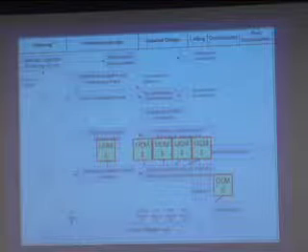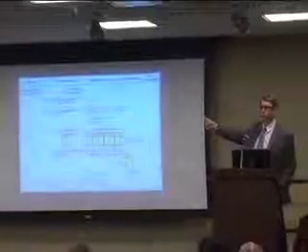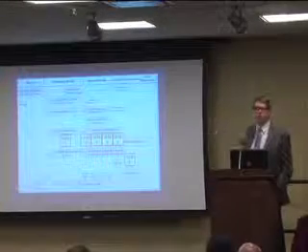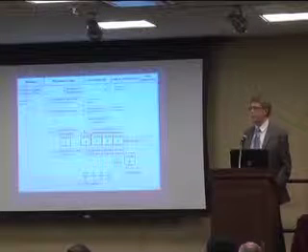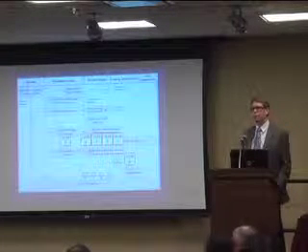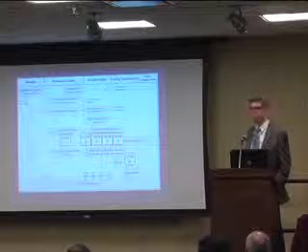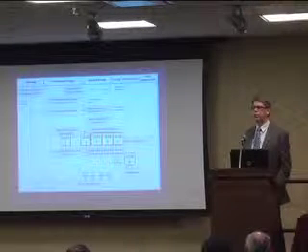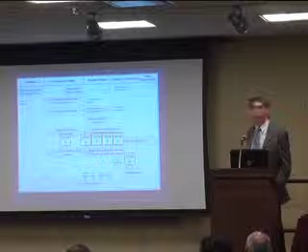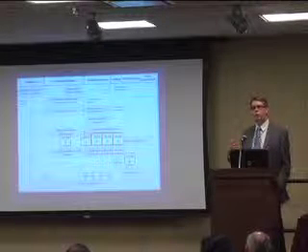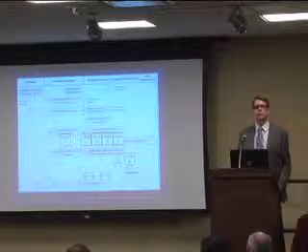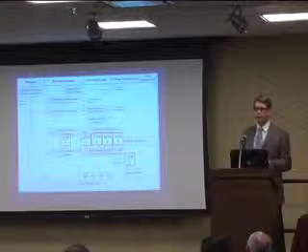And on this slide, I'm just showing the 6 typical phases of the project development process. You start with planning at the left, then you have preliminary design phase, detailed design phase, letting, construction, post-construction. So based on the experience that we gathered talking to folks around the nation and within Texas and many utility projects that involved utility coordination, it really makes a lot of sense to start as early as you can, as early as you get information about utility conflicts, and start populating that matrix and keeping track of that.